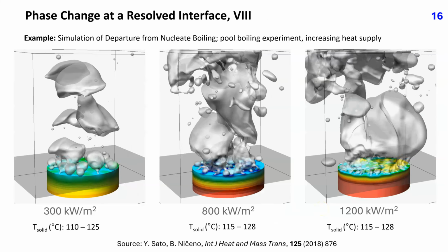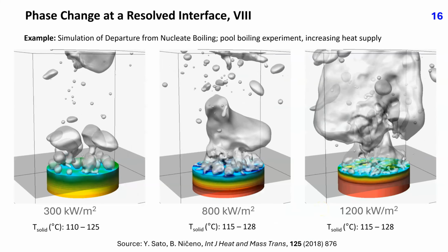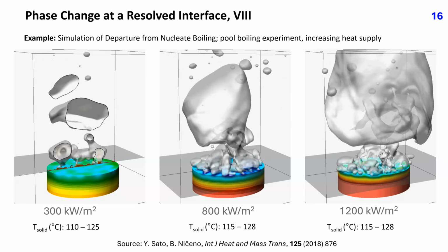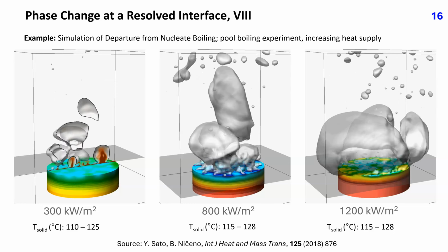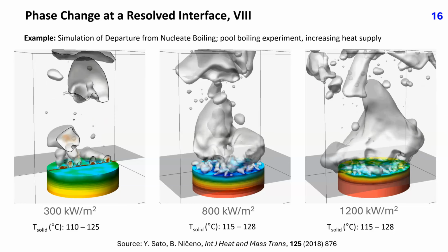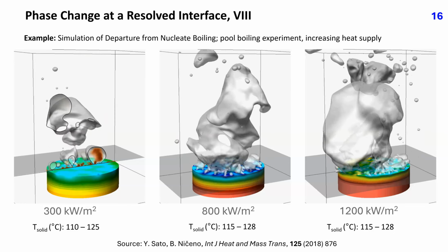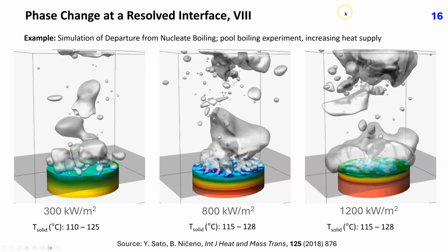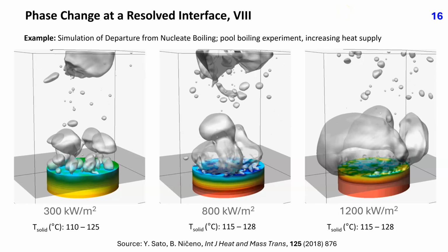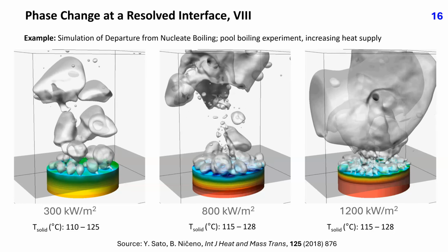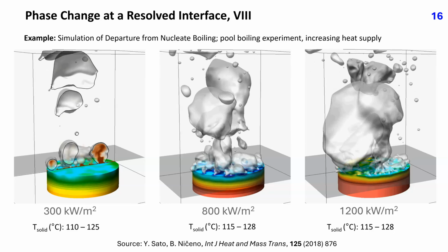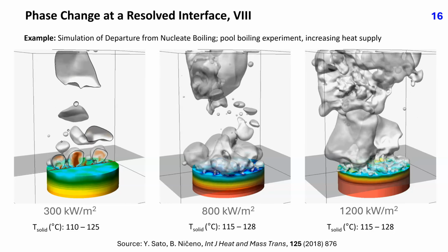With the increase in boundary heat flux, the temperatures in the copper block increase. This leads to more nucleation sites at the interface to liquid becoming active and a faster growth of bubbles. Many bubbles coalesce to larger bubbles, which form and also break up as they rise. At the highest boundary heat flux, we see events of large vapor clouds building up and departing. The temperature and the local heat flux are highly non-uniform at the solid-liquid interface due to frequent departure of bubbles from the wall.